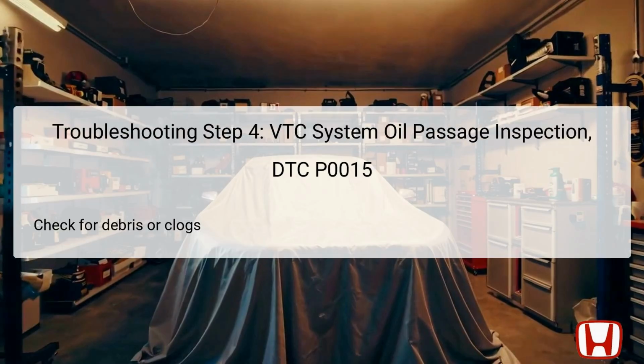The final step in the troubleshooting process is the inspection of the VTC system oil passage. This area is critical for the correct flow of oil to the components involved in the variable valve timing system. Use appropriate diagnostic tools to check for any debris or clogs that could be obstructing oil flow.